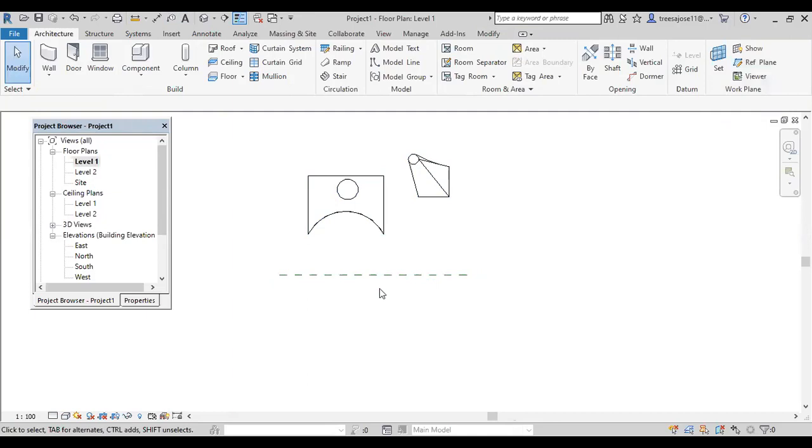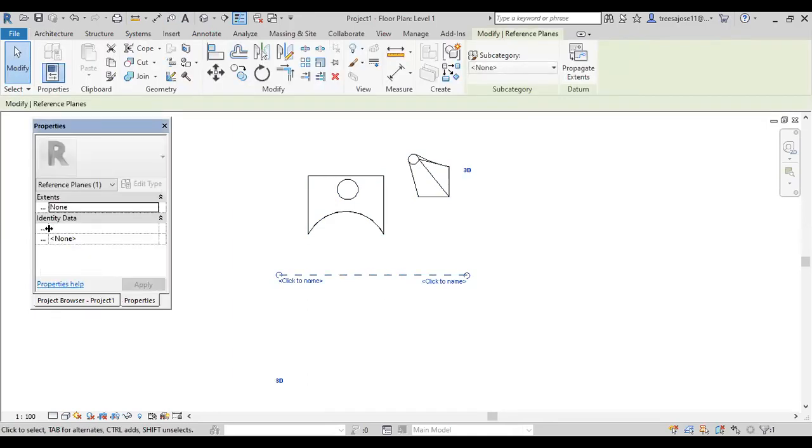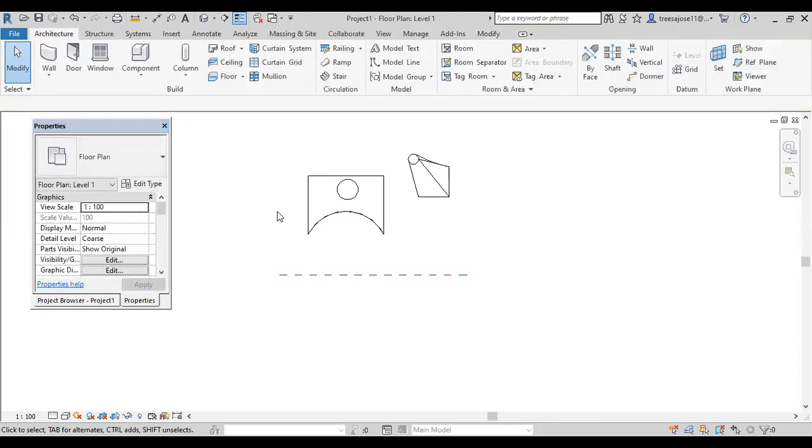Okay, then I select that plane, then go to properties. You can put a name for that reference plane. Okay, I think I will put the name as A plane. I will explain why I have made that one. Then I use the revolve command, because I need a 3D structure with a complex shape with a circular model. In that case, we go for the revolve command.